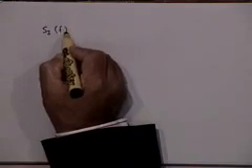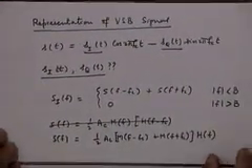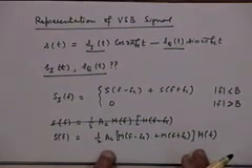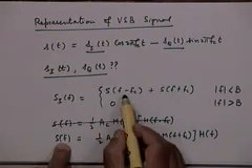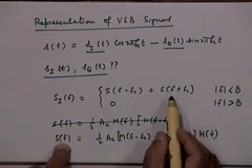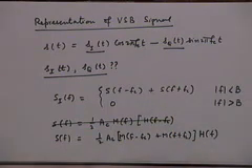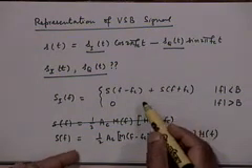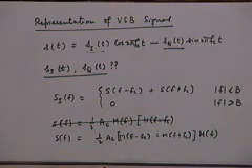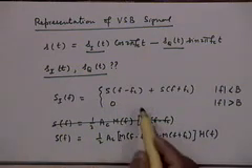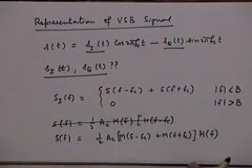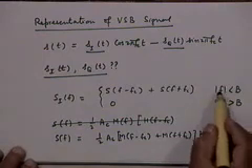So this would then become S_I(f). Would you be able to tell me what it will be? If you remember, we had also discussed the nature of S(f − fc) + S(f + fc). We had gone through this step when we looked at the demodulation of the VSB signal, and that contained 4 terms, obviously, because two terms come from here and two terms from each of these, and therefore you get 4 terms, out of which only 2 terms were in the baseband, which is what you want.